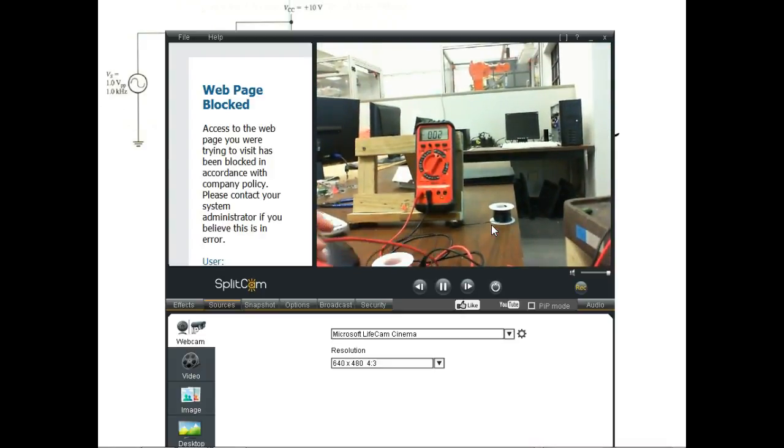I'm going to come over here and look at my base voltage. Instead of being 1 volt, it's up to 2.7 volts. Instead of being 1.7, it's up to 2.7. See that? Which means my emitter voltage now is way up to over 2 volts, 2.6 volts. Transistor saturated, so it can't. So look, it's not even dropping 0.6 of a volt.